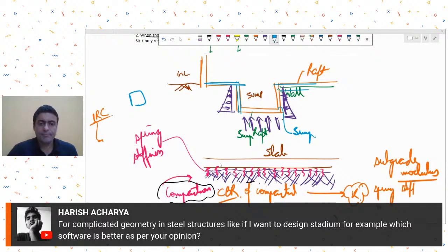But, just let me see something. I'm just checking one thing in ETABS. Okay, yeah. So you are able to bring a DXF file in quite well also. But then load application for slant members, or selection of members that are not in your plan view, can be slightly difficult in ETABS than STAAD, I would say. But because STAAD has other issues related to input-output and other design issues, maybe I would still suggest ETABS is a better option.